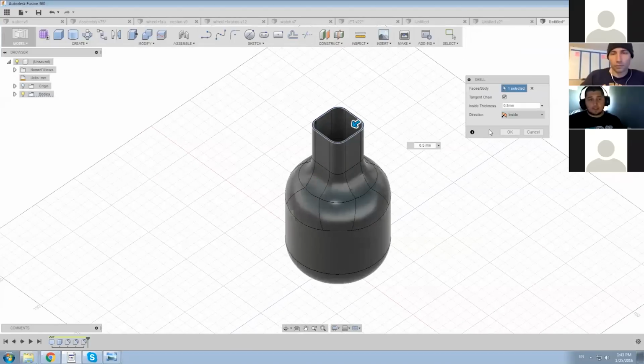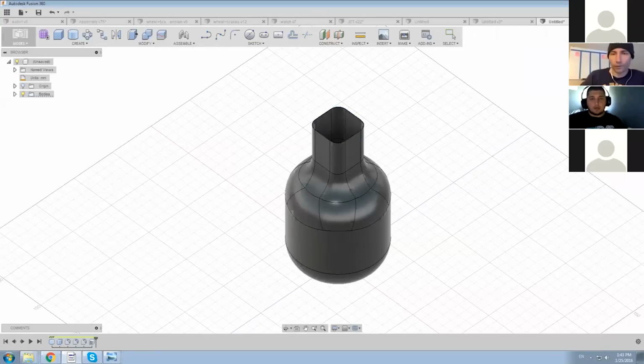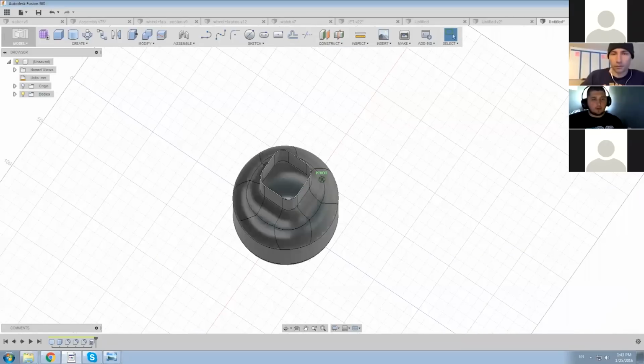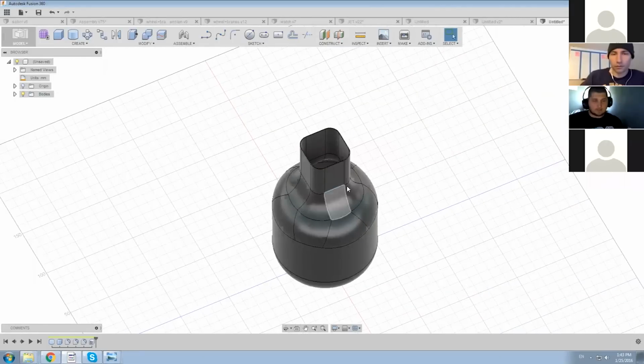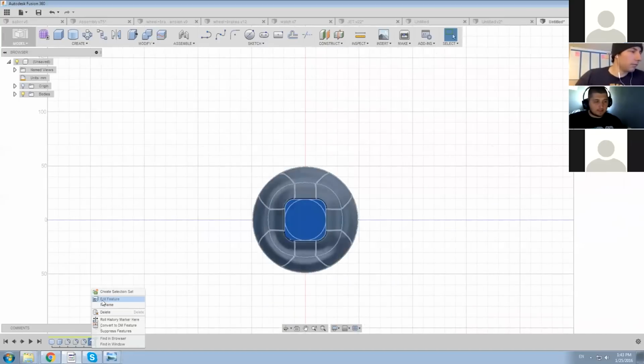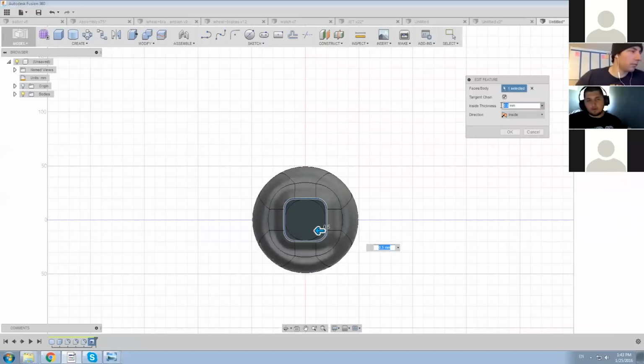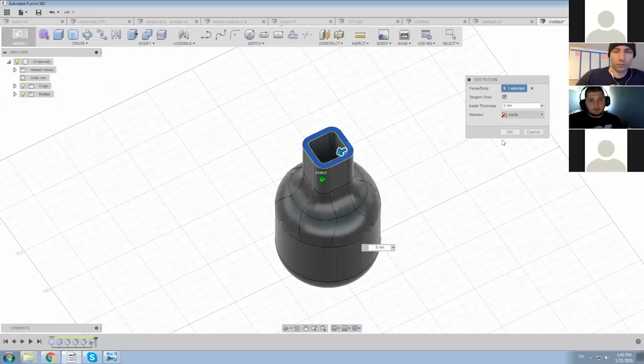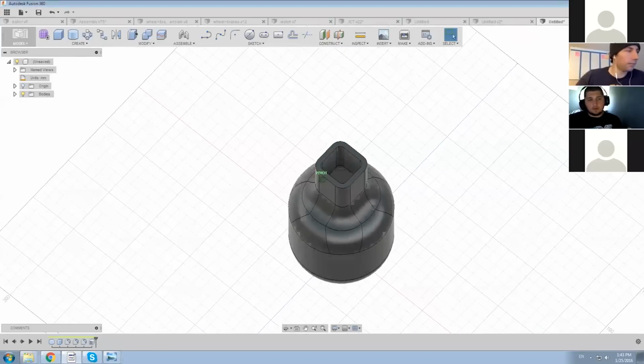It has certain limitations when it's crazy shapes, too thin of walls, too thin or too thick, or intersecting, stuff like that. But generally, taking your design and making it hollow, and then just creating the necessary support structures, it's really easy. Plus, you can definitely go back, let's say, and say, hey, I didn't want it to be 0.5. I actually want this shell to be 5 millimeters. And it is 5 now. Yeah. You control the thickness.